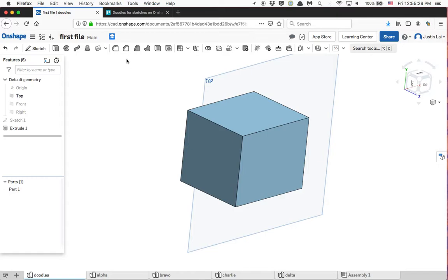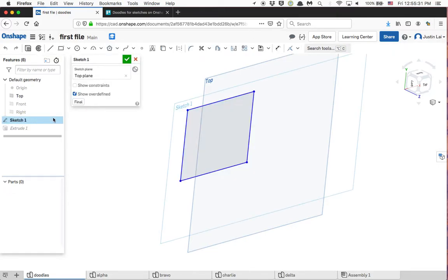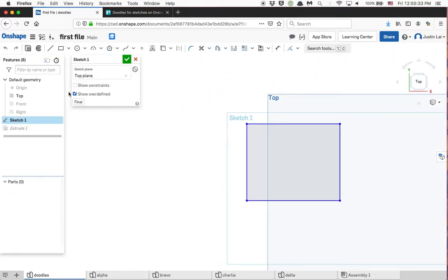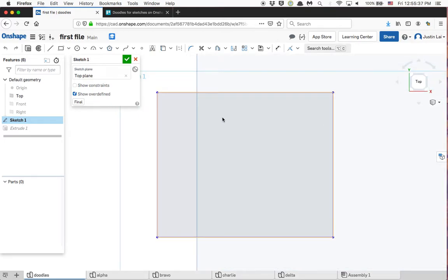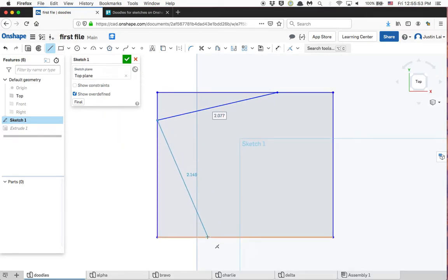All right. One more thing, to really drive this concept home. Let's go back. You have your rectangle. You either built the rectangle from scratch, which in reality you would never do. You would just use the tool. We can double check here. And what we're going to do, just a little bit of practice. We're going to pick our line tool. And we do want to make it coincident. So we're just going to make our segment so it just intersects at some point.